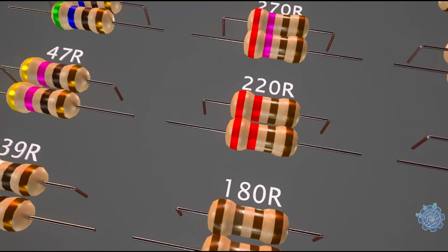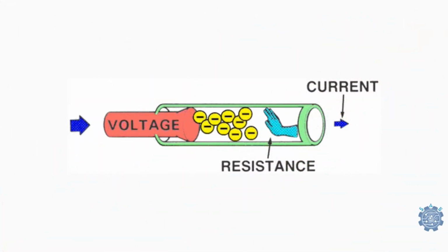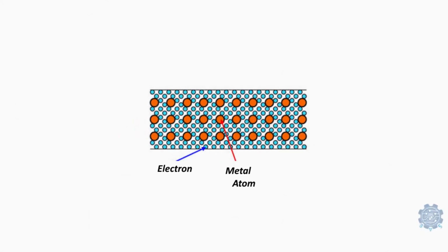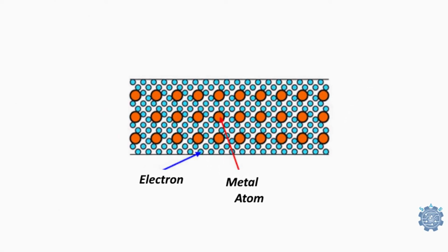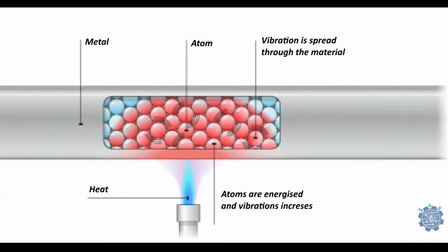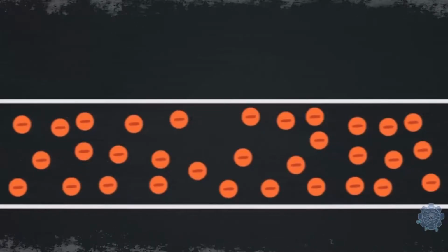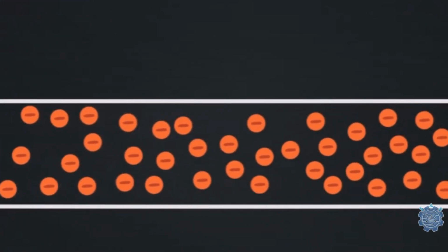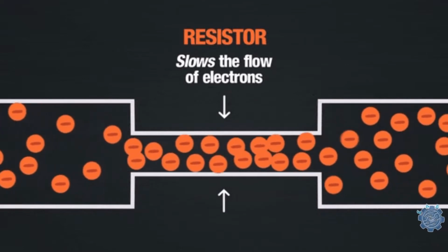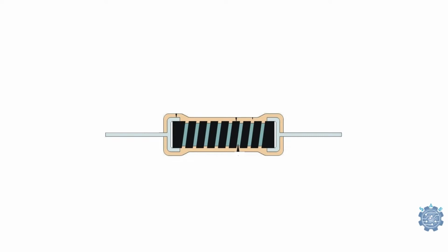What makes the resistor oppose the flow of electric current? Each resistor is made from different resistive elements that catch in their structure a part of the electrons from the electric current flow. Some electrons collide with the atoms of resistive materials and some escape and pass through it. The electrons that collide transfer some of their energy into atomic vibrations, which produce energy in heat form in the air molecules or heat sink device. The fewer electrons pass through the resistive material, the more it opposes the flow of electrical current and the value of resistance is higher.